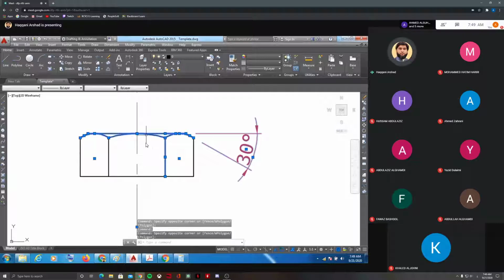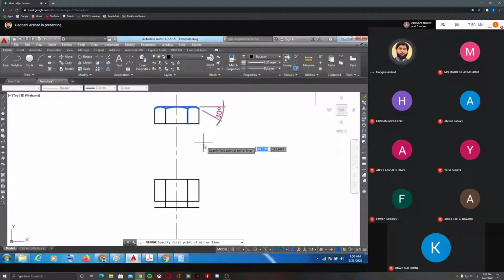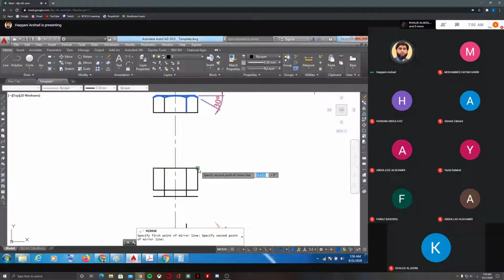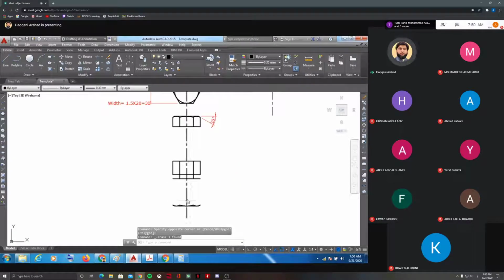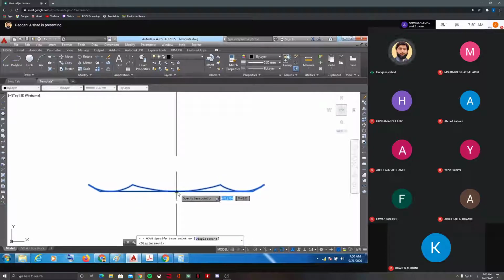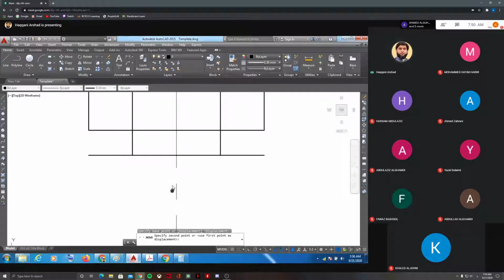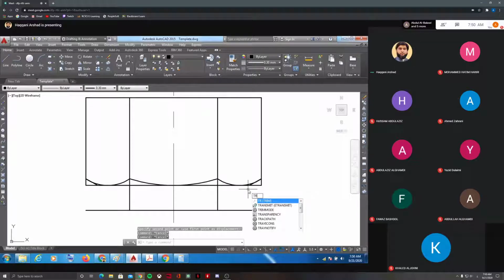Okay. Now what I'm going to do is mirror it because it is the opposite side. You can mirror it, but there is no center, so somewhere I will mirror it here. See, I got the arcs here. I just copied the same thing from the bolt and mirrored it somewhere here. Then I simply move this from this midpoint. See, I'm just saving the time. I'll keep it here, simply. Then I'll just trim this.